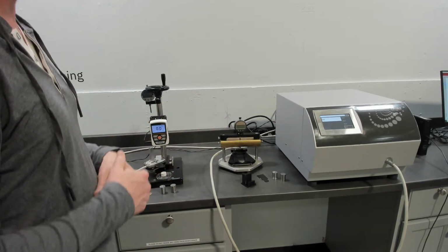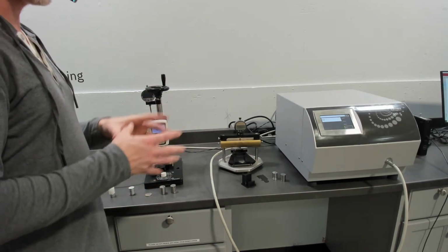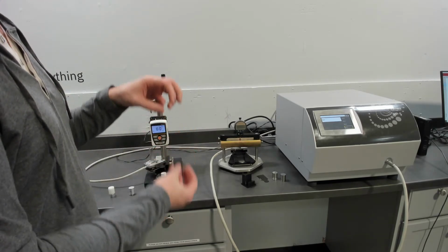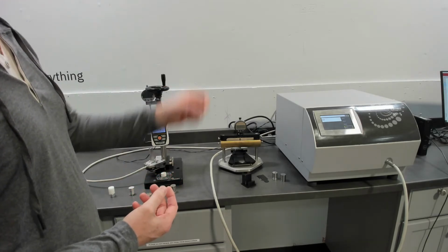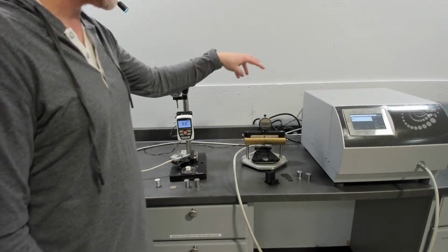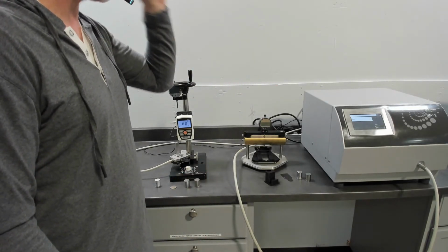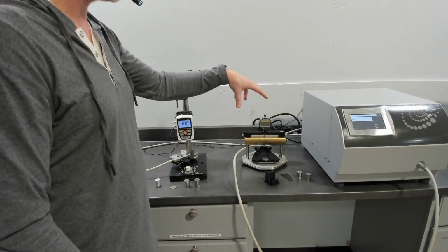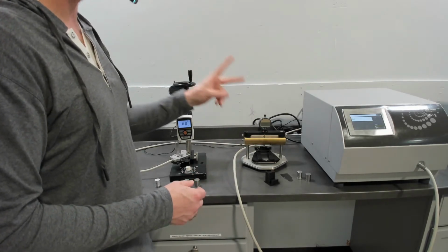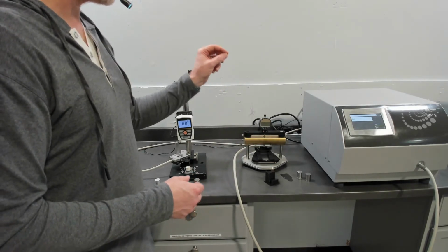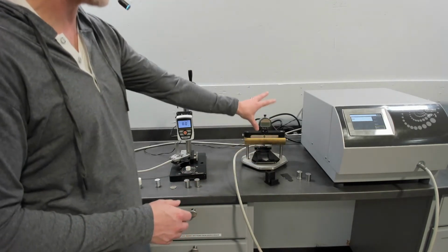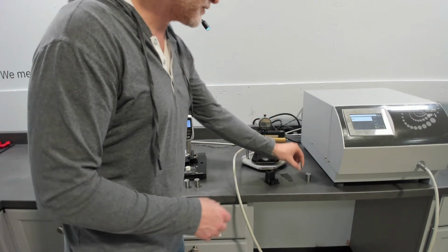And what is a testing module? It's a variation of the principal approach of transient plane source. In this case, it's a variation of the one-dimensional heat flow method that's within the TPS method. One of those modules is the transient resistance. What that means is we're measuring the thermal resistance, and we've extended that from sensor to sample to between two materials. So we've packaged that with our basic TPS sample holder with a few basic additions and two standardized